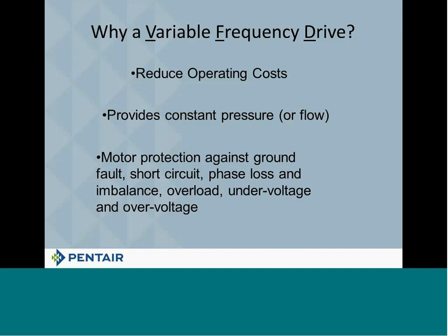You don't need to. Now, normally when you do a 3-phase across-the-line system, you need to do an imbalance test. When you have a drive, you don't need to, because the drive makes the electric going down to the motor, and it balances each one of them out. You don't need to worry about that. If something should happen and one of the legs falls out, the drive shuts down. It's that simple. It will not single-phase or 3-phase motor and cause you to spend a lot of money.